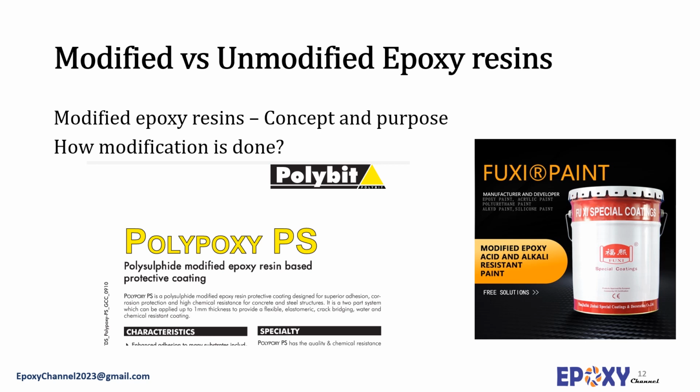In paint coatings, the modification includes reacting with fatty acid derived from oil to yield epoxy esters, which were cured the same way as alkyds. Typical ones were L18, 80% linseed, and D4, which means 40% dehydrated castor oil. These are often reacted with styrene to make styrenated epoxy esters used as primers. Here, organic chains may be used to hydrophobically modify epoxy resins and change their properties for primer use.